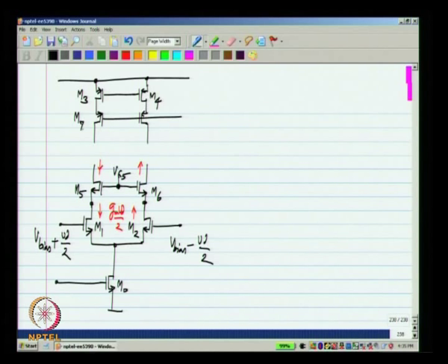Let me call them M7 and M8, and this is the current mirror, and this is Vg7, which I will connect to some voltage. For now, I will just say that Vg7 is such that all these transistors are in saturation. Similarly, Vg5 is such that all these transistors are in saturation. So, now I connect the two things together and take my output from there.